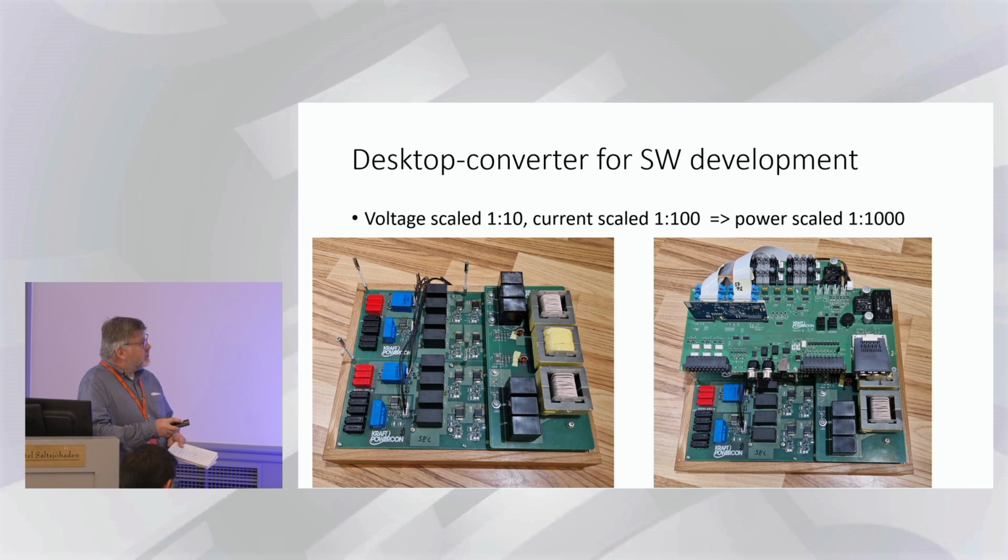This is the control PCB, where we have a CPU card, and this is the electrical interface that we use in the desktop. Here we have the optical interface that we use in the big system. This is some interface to the outside world: field bus, USB for setup, and CAN communication when we have several modules in parallel.